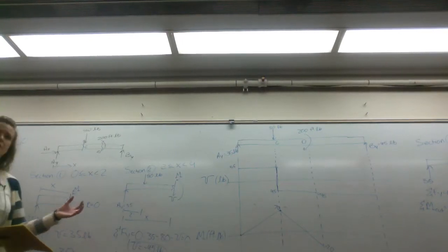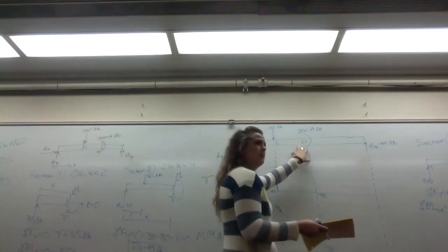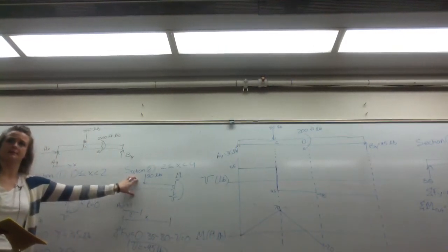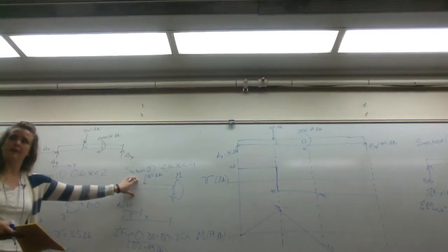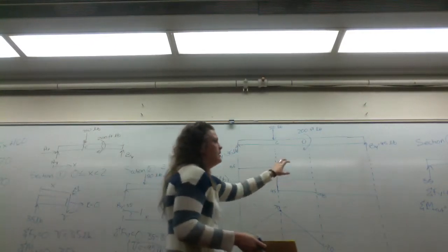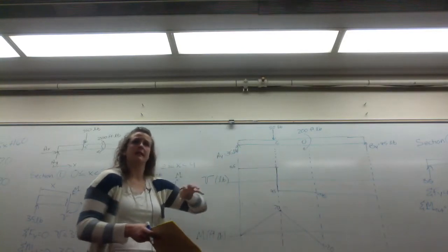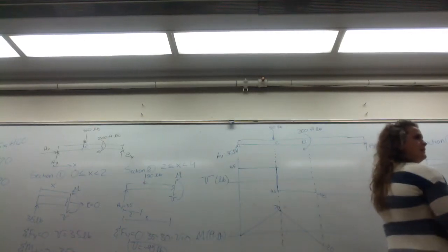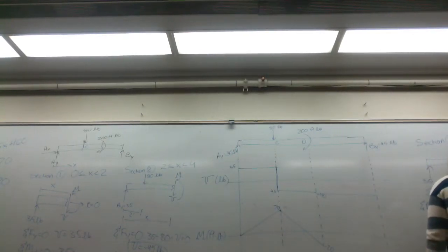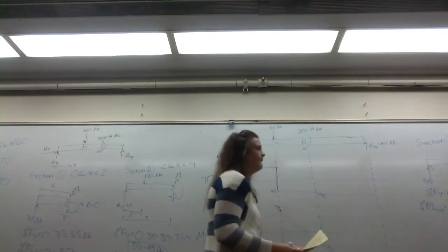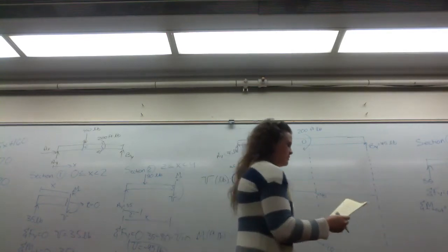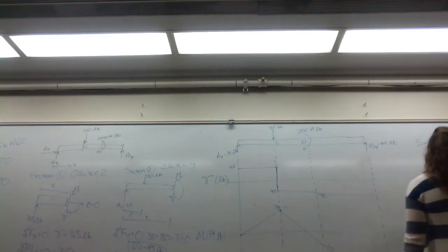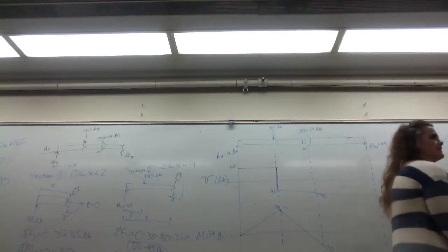But we also have a loading condition here. We have an applied moment at D that we did not take into account in our second section, as we cut right before. Moments are free vectors, and they act independent. That's why there is no distance attached in our moment. So in our moment equation, we have negative 200, the clockwise moment, minus 35x. X is my length of the beam.